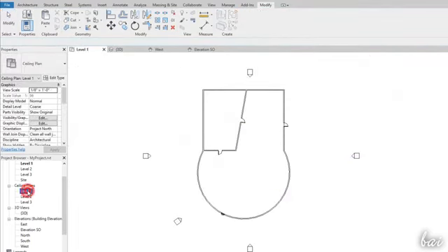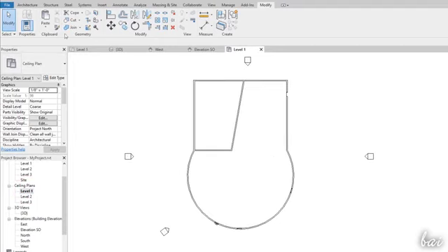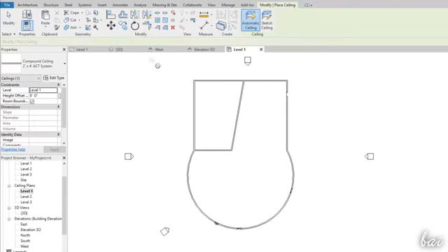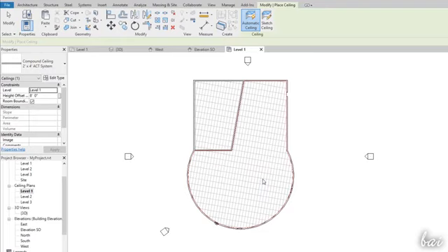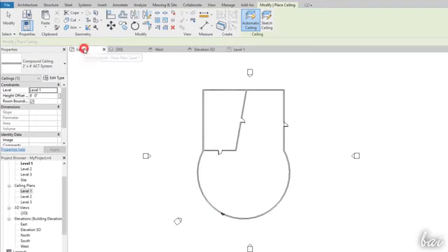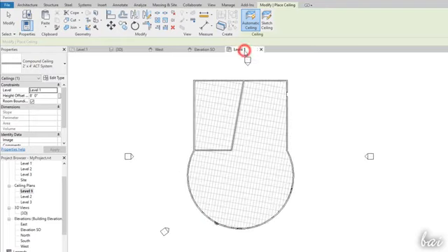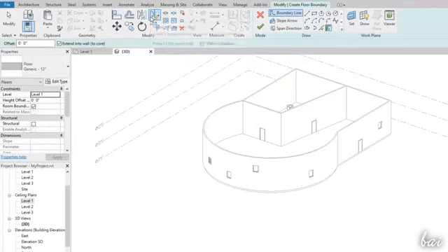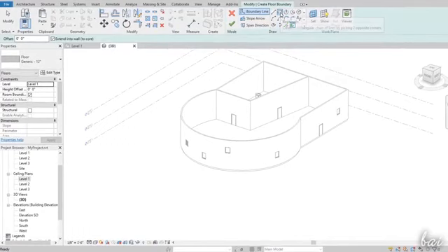Once the current floor is finished, you can apply the ceiling to it. Enable the Ceiling tool and click within the wall contours. The ceiling created is usually kept hidden and is visible only on dedicated 2D views called ceiling plans. At this point, you can continue with a second floor or finish with a roof.